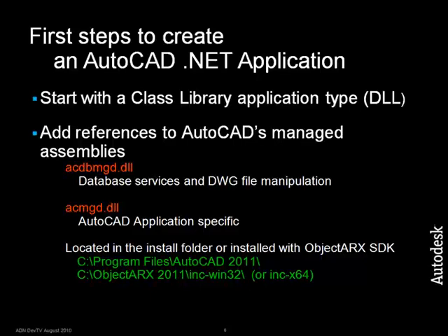You will find these DLLs in the same directory where the AutoCAD executable is, or if you have the ObjectARX SDK, it will be in the lib-win32 or 64 directory. I would recommend that you install the ObjectARX SDK and reference the files from there.